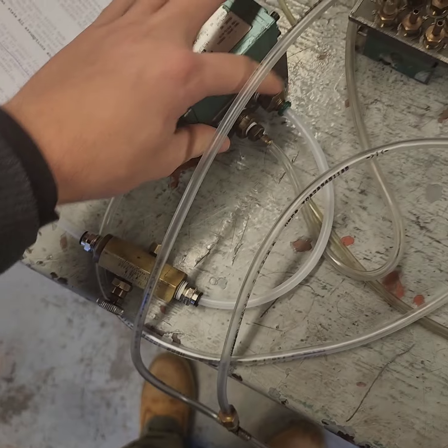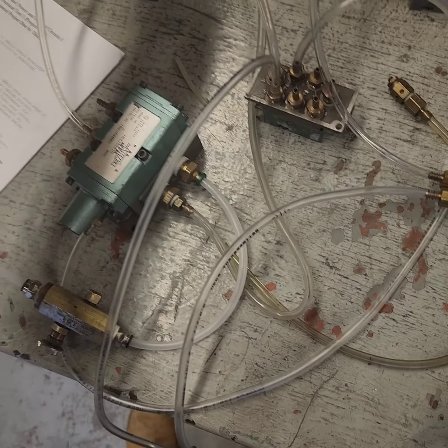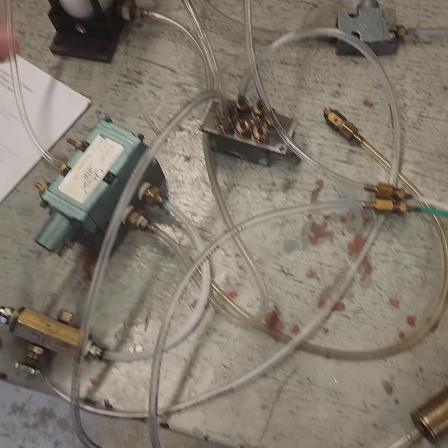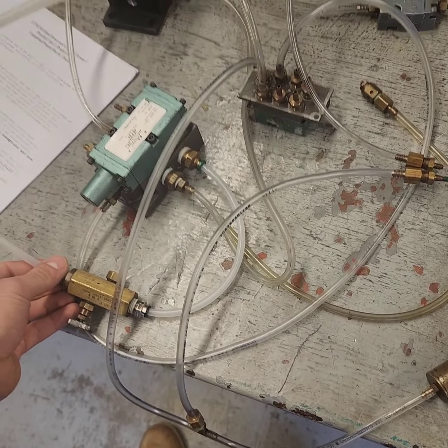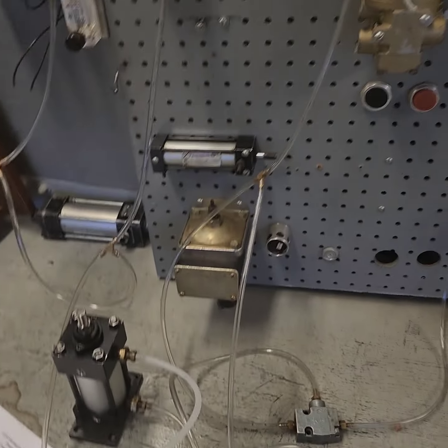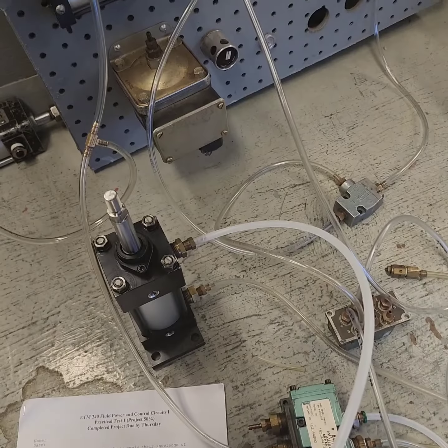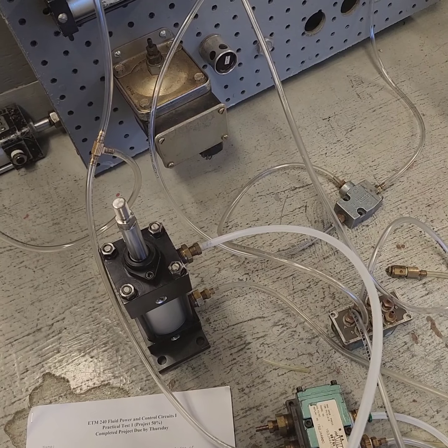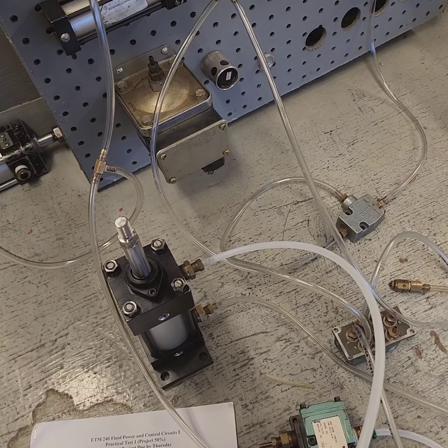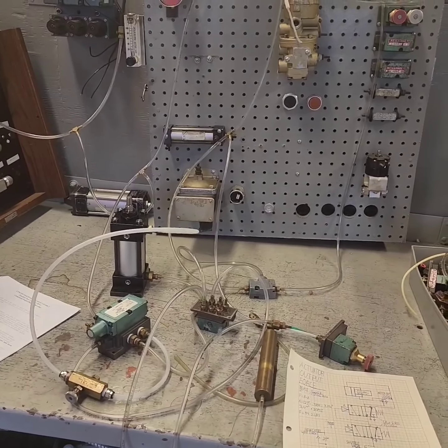And then we have our A and our B. A is going through the metered control to the extension side, so that when air comes out, it hits the flow control and it'll slow down the extension speed. This is replicating our limit switch. When you press that, the timing function will kick in, and only when that's pressed, because it's simulating a limit switch.